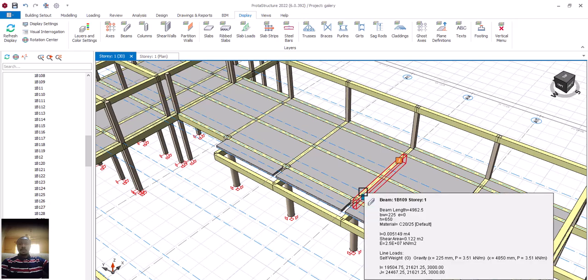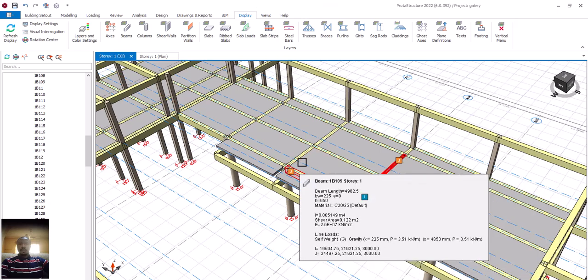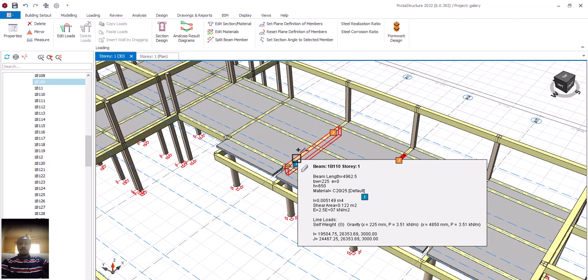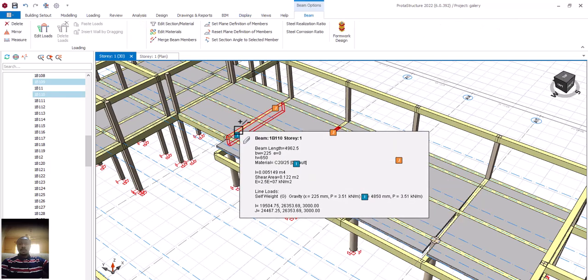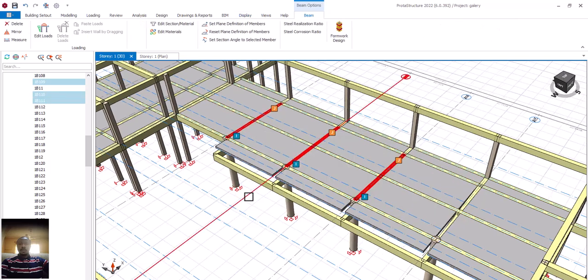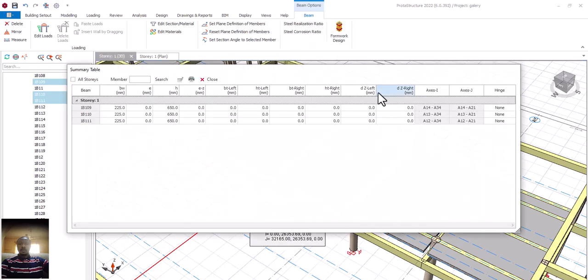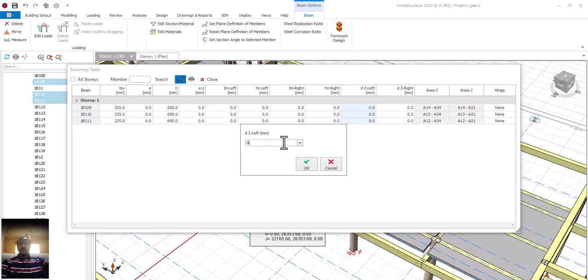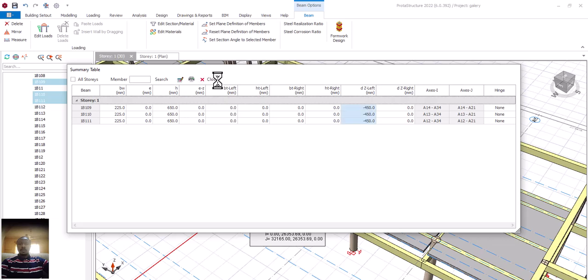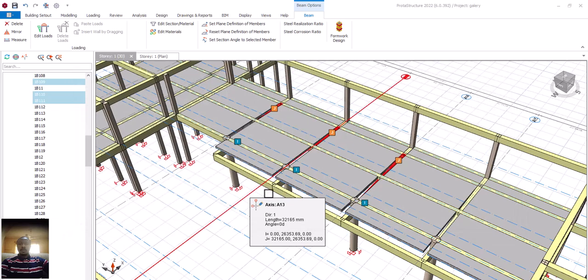So click on this one, select this one, and also press my Control key, select this one and also this one, then right click. I'll click on the property. Okay, then this left should be I, I guess. Left should be I. So then click on this. There's minus 450. Then click on update. Okay, and then let's come up. Then click on close. Let's see. Okay, it has all worked, so that's fine.